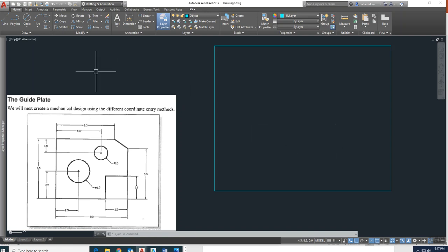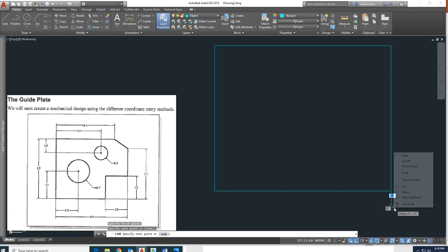Some things here. So I'm going to hover over to my line command, left click it, and come back to this edge here, and I'm going to create a construction line. As my crosshairs hover over this endpoint, I'm going to left click it and come all the way down. The units don't necessarily matter because it's nothing more than a construction line. And I'm going to left click, right click, and hit enter. Left click, enter.